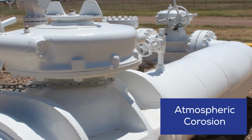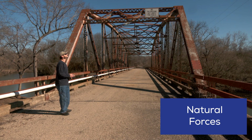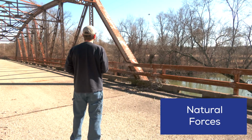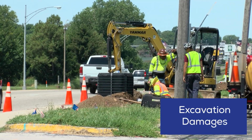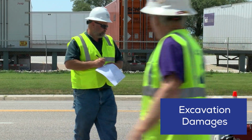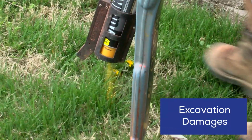To prevent atmospheric corrosion, paint facilities. One common natural force threat is flooding. Consider increasing the frequency of leak surveys at river crossings. Excavation damages are costly and threaten the safety of your system. Improving GIS data can help locators provide accurate locates of your underground pipeline facilities.